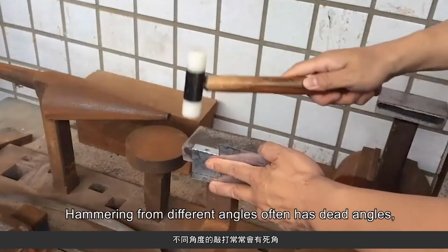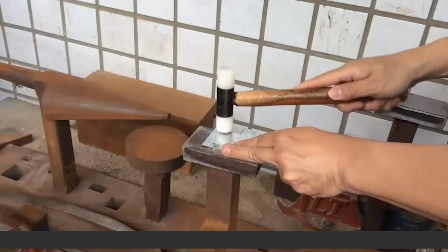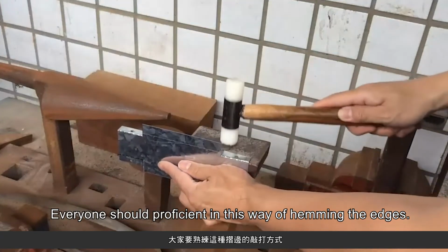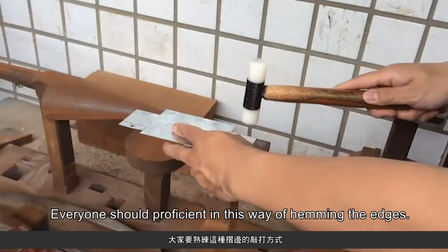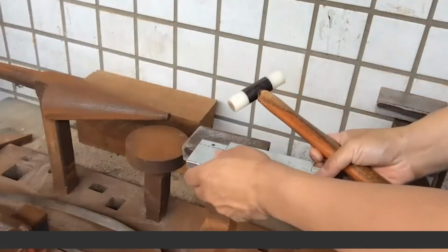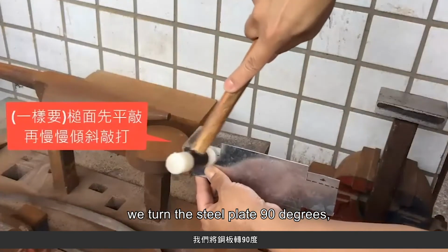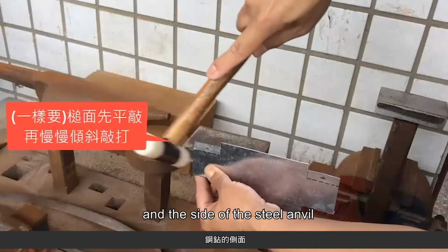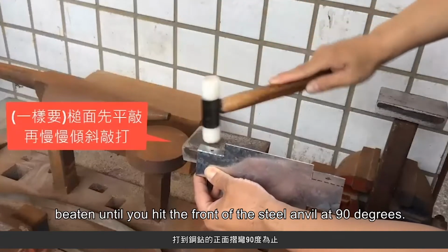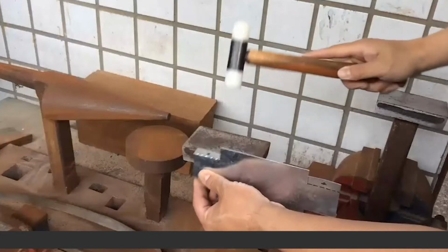Hammering from different angles often has dead angles, so we often need to change to different hitting points. Everyone should be proficient in this way of hemming the edges. At this angle, we turn the steel plate 90 degrees, and the side of the steel anvil is the front of the steel plate. Slowly tilting the hammering, beat until you hit the front of the steel anvil at 90 degrees.